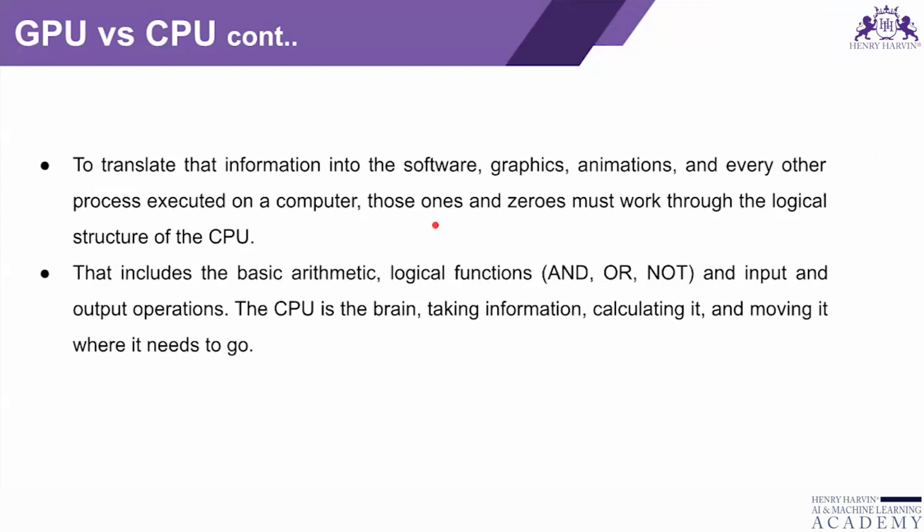Whenever we want to do any task, either we have to select yes or no. Just like that, the computer works on that basis, that is one or zero. If we understand the OR gate, it is adding two pieces of information: 1 plus 1, 1 plus 0, 0 plus 0, or 0 plus 1. So in this OR gate, it is adding the two bits. And in the AND operation, it is just multiplying the bits. NOT means just negation, the opposite. If it is 1, NOT gives 0. If it is 0, NOT gives 1. This way, some basic arithmetic operations are done in the CPU.